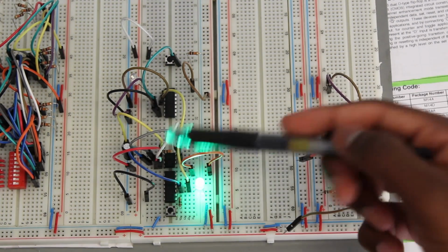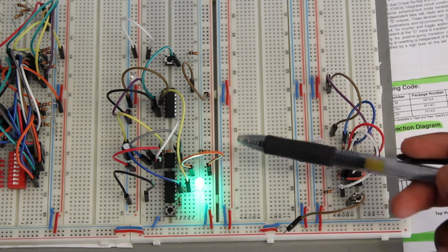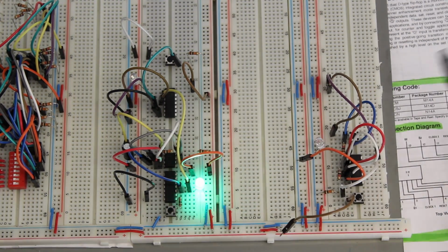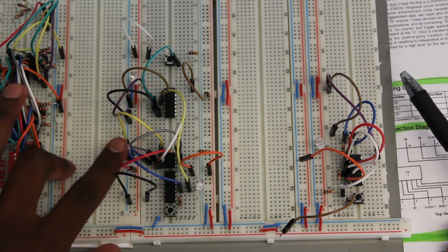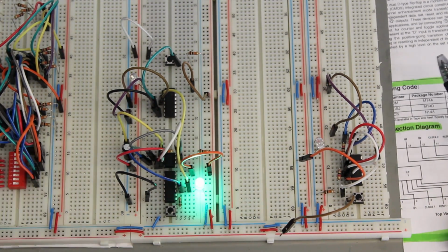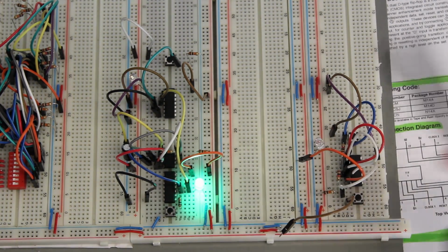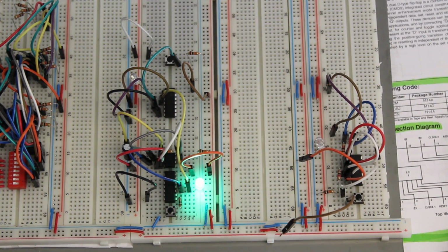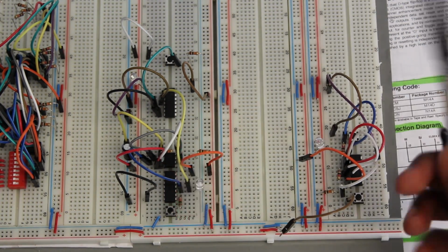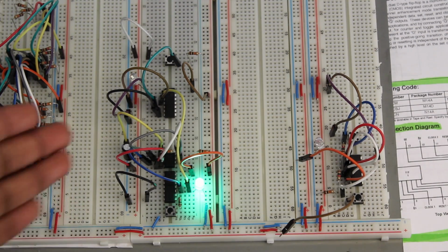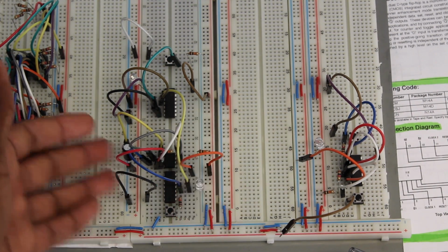So here's the clock circuit that we built previously, and you'll notice that the LED is actually beating much slower than before, and that's because I raised this capacitor up to 100 microfarads. It was 10 microfarads previously, now it's 100. And I did this so it approximately makes the beat about 10 times slower. And another way you could do this is by putting a resistor between the capacitor and ground.